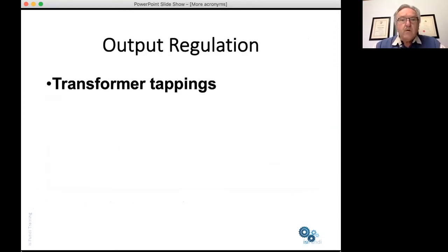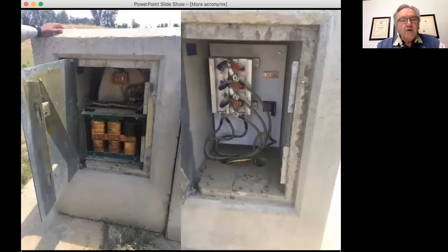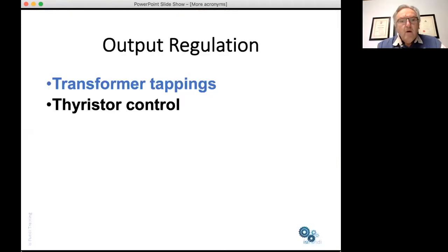So what sort of control do we have? The simplest control, which is something that we hardly use in stray current situations, is that of a tapped transformer. So this gives us a constant output voltage. And here you can see an example of a system that is installed. There is actually a rail in the background, although you can't see it hiding behind these concrete bunkers. And here you can see that we have a fairly heavy rectifier, which is pushing current back to the rail.